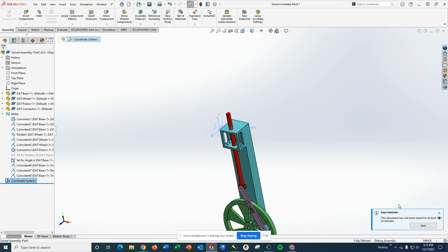You should also make sure that those are true for whatever it shows you, because sometimes when you have to set a coordinate system up, it'll show you this, and you might actually see that Z is up and Y is forward, or one of the arrows is not pointing in a standard direction. And while that won't affect the number measurement, it may affect the positive or negative value of it.